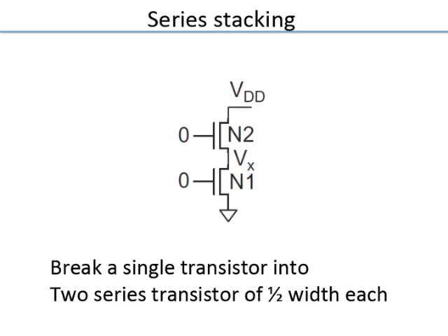The overall system delay doesn't change, or system delay does change, but it's a trade-off you're willing to make because of the gains. Remember when we said in sizing, when you do minimum delay sizing, you can end up with an energy which is pretty large. And if you back off from the minimum delay sizing, you can get a substantial reduction. A small back off, a small increase in delay, can reduce energy quite a bit. So that kind of trade-off, you might want to do.